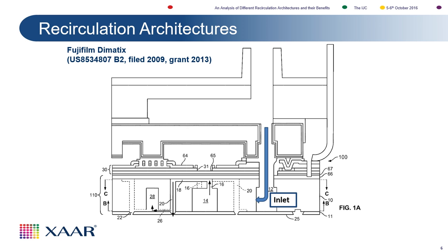There's the ink inlet, where the ink comes in. It then goes to a submanifold, where the ink is divided and gets access to the chamber. Then they have the chamber, where actuation occurs, and then it goes past the nozzle, out through the submanifold, and completes the circuit. So, as you can see, quite a complicated ink path, and this is typical for a roof mode type actuated device.